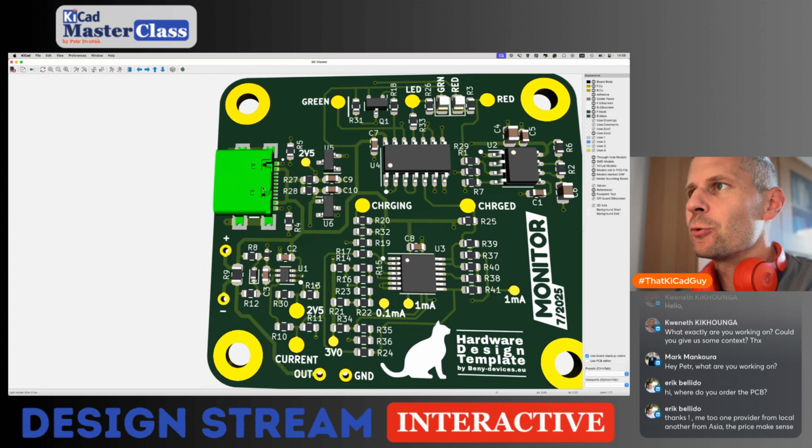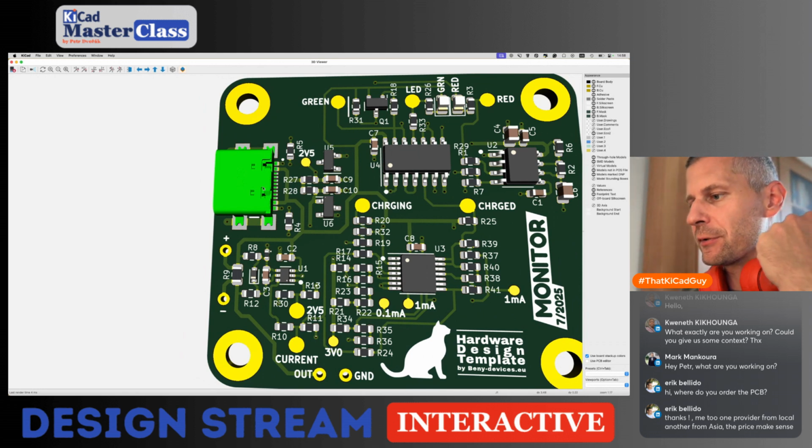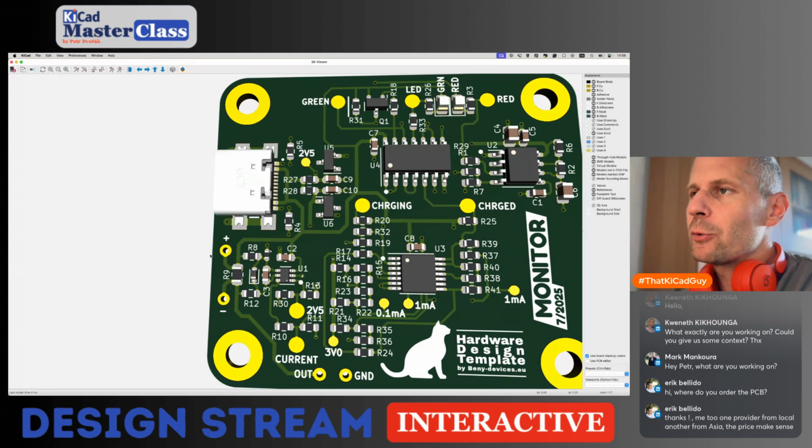I didn't want to use the USB port for the initial testing because it's more difficult to test. When I use the testing wires, I can connect my laboratory power supply, and with a proper current limit, there is no safer solution.